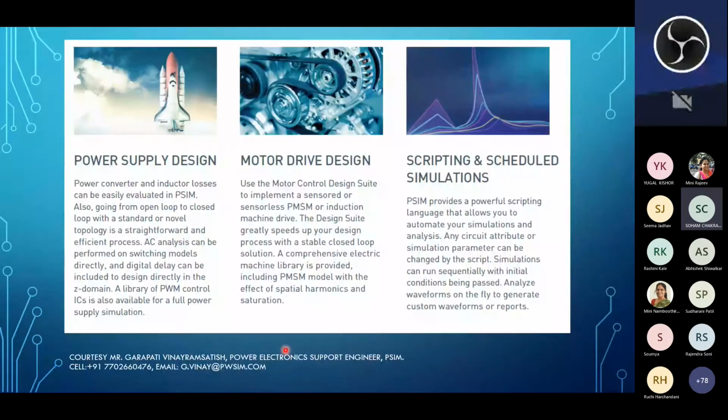So you can see here, PCM can do power supply design. So if you are designing power supplies based on power electronics, you can do power converter and inductor losses calculation in this PCM. Open loop and closed loop simulations are possible.